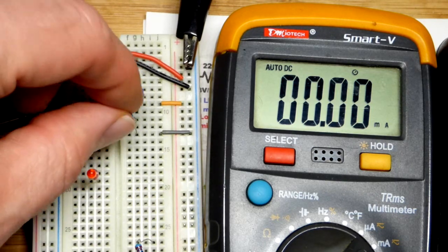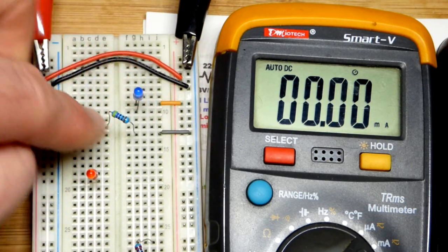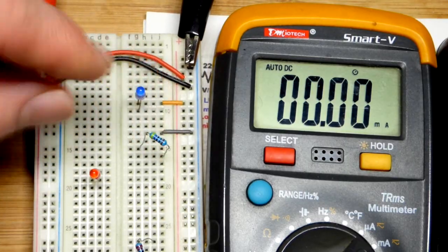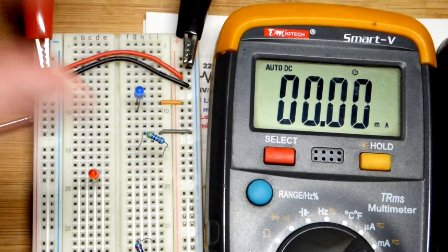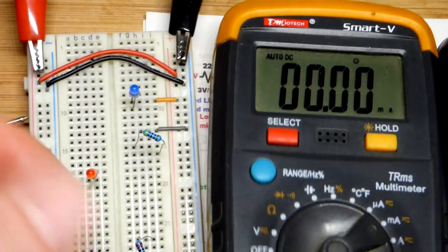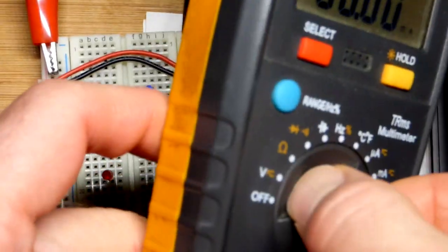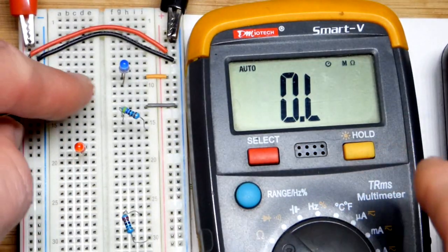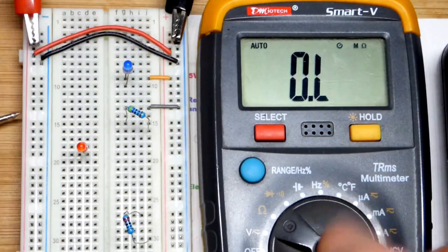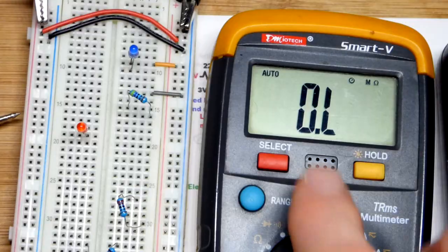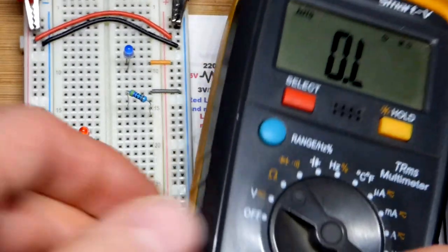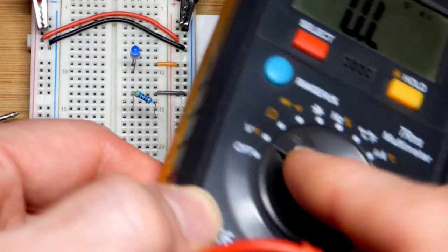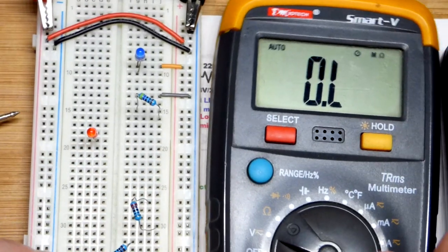Now, we don't have to move the resistor. It comes to a dead end, but when you measure the resistance, you don't want voltage across it. So we will move it there just to be extra safe. But we didn't really need to, because one end was already coming to a dead end. The power supply could not push any current. So, oh well, I just set the meter to the resistor symbol. That's the omega symbol for ohms, which is the unit of resistance.